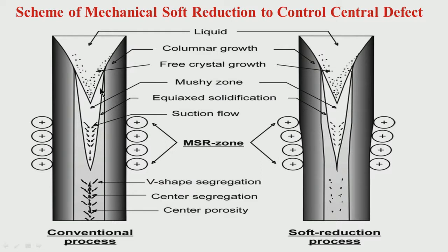If you put the pressure beforehand, it will be of no use. If you put the pressure after solidification is over, it will also be of no use, rather it may generate cracks. I will come to it later on. What is important is you put pressure only at the final stage, in the area where the final solidification is taking place.